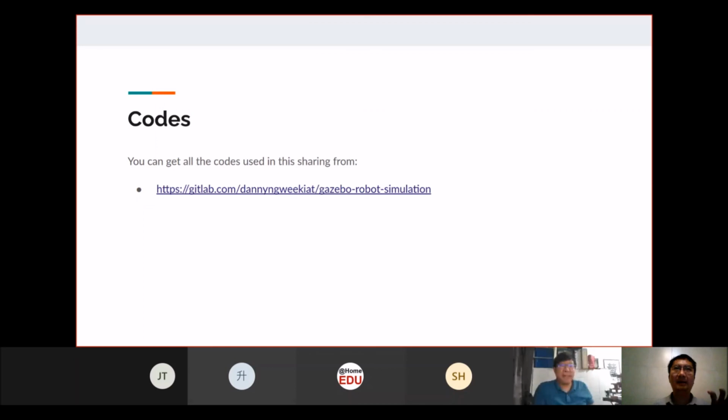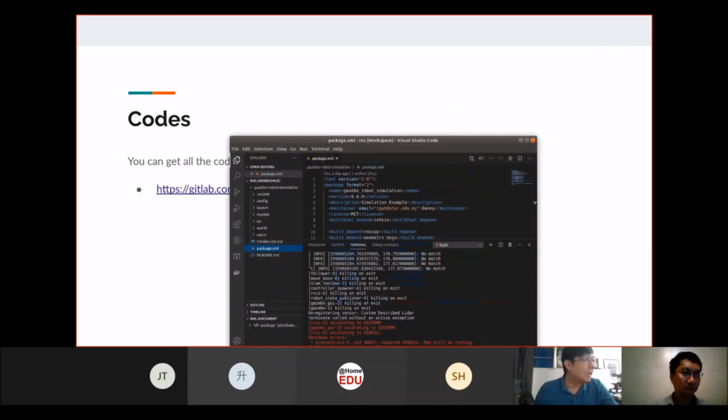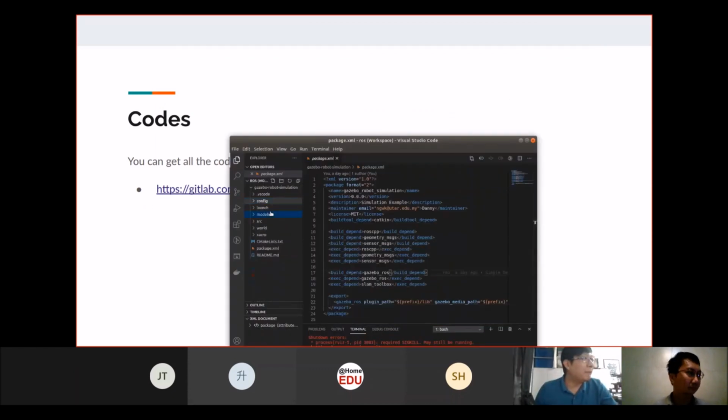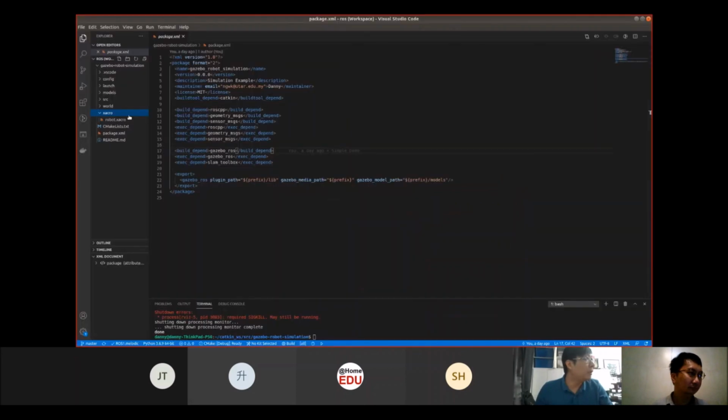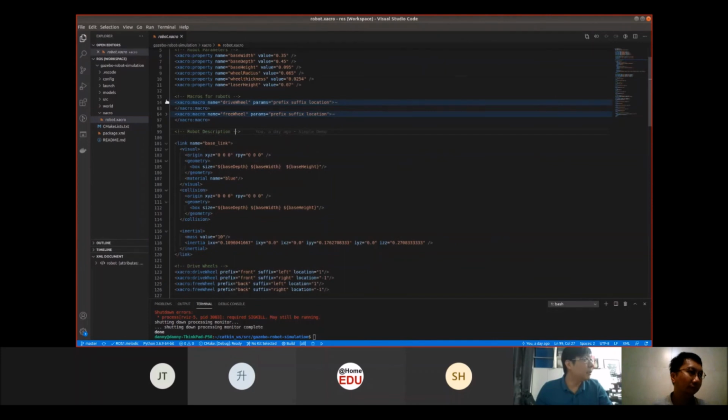But how realistic the fidelity of the grab is depends on the Gazebo parameters you use. Actually in Gazebo itself, you need to key in the friction parameter of the material. Let me just show you this. It's available in the SDF file and also the URDF file. So when you define, for example, your robot views, let me just go to robot views.